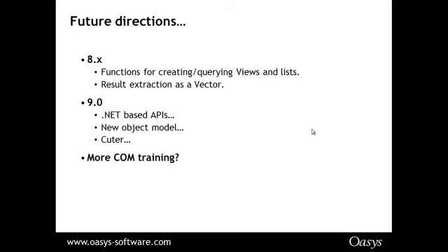So if we want to query nodes, you'll be able to extract the node object out, and then query various attributes on it, or edit some of them and reinsert it back into the database, instead of having to work with GWA syntax, for example. Those are the kind of things that we have planned for the .NET based APIs that we might release in the future.